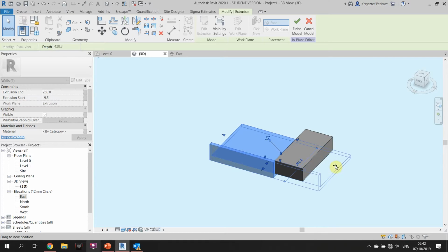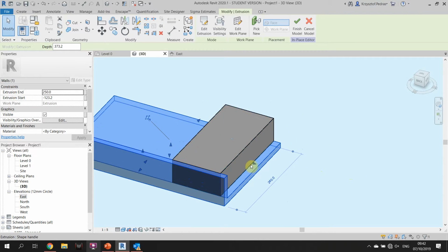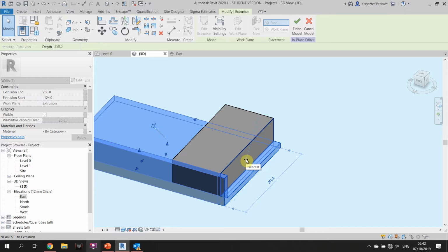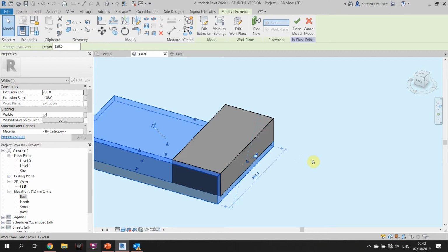And you can see that as I hover over the object, it starts snapping to the side. I'm going to zoom in on this one. You see it starts to highlight and a little line is created. That means that it's going to get the dimension equal to this one. So if I let it go, it's going to trim it exactly to that place.